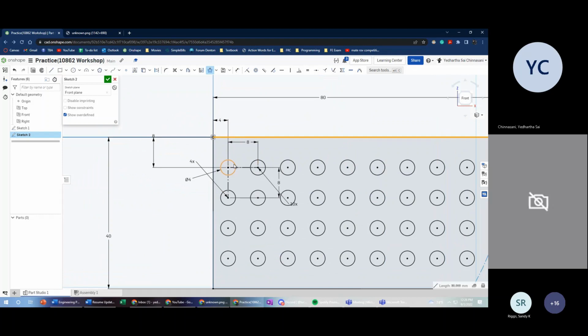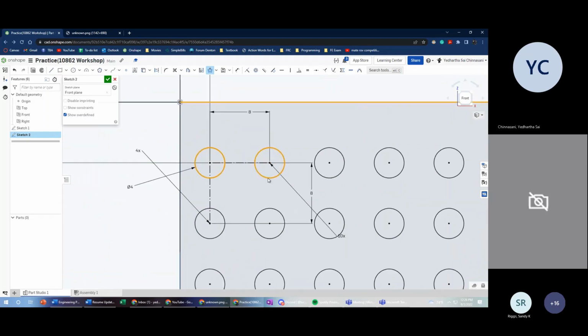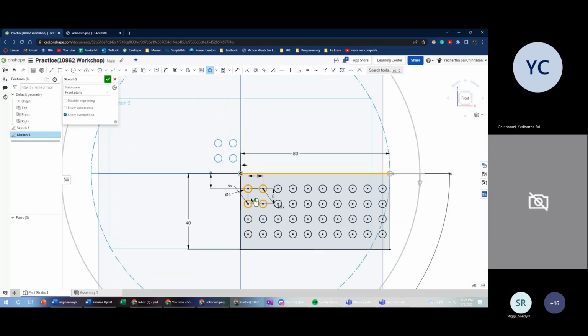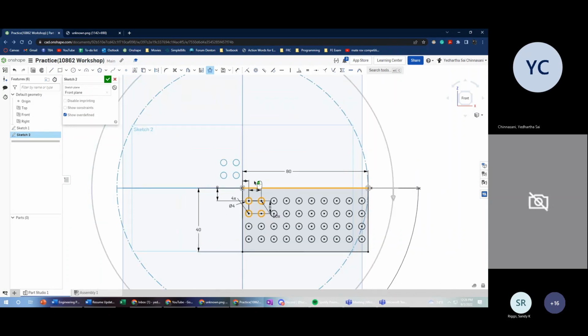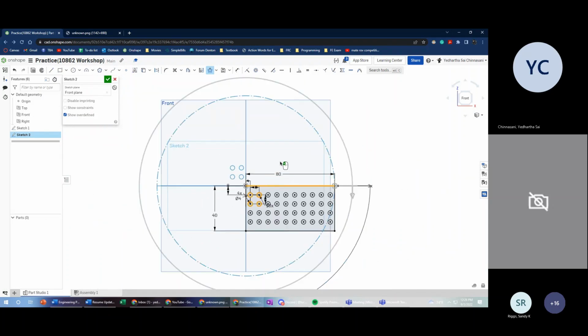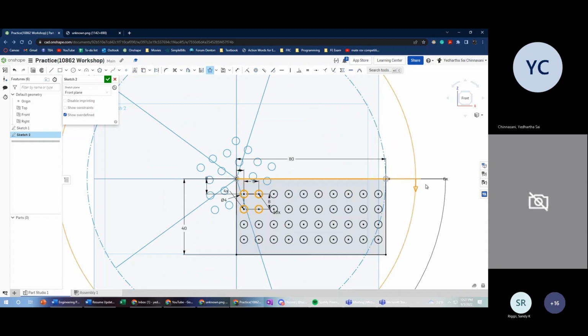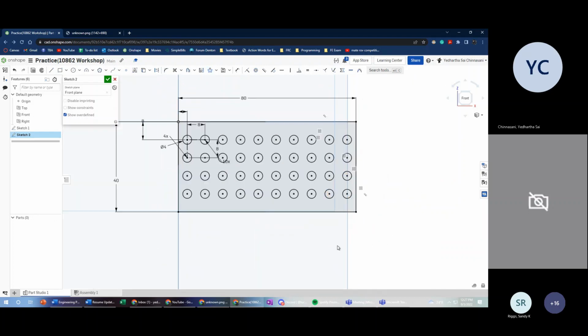And it's going to ask you the entities to go around. So I could click on all different entities, right? And it will project those entities, and you press enter, and you can change the value to like 6 or 7, and you'll see that the circles are made. In this case, 4 is enough, or 5, yeah. So that's how a circular sketch pattern works. Basically, that's all about sketching.